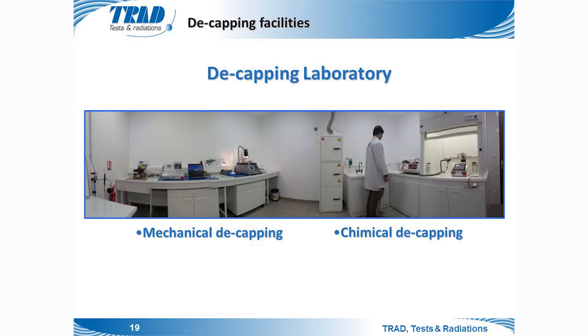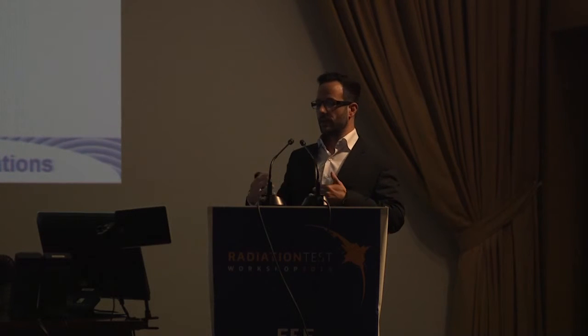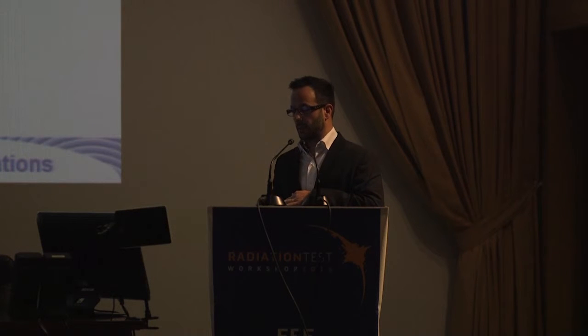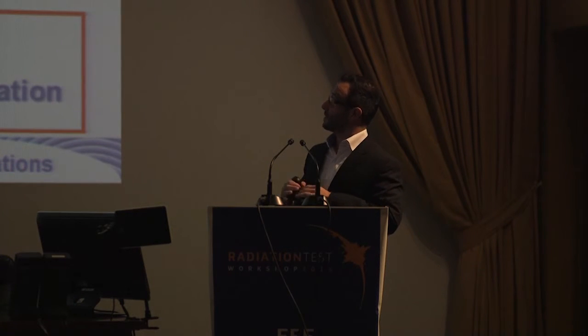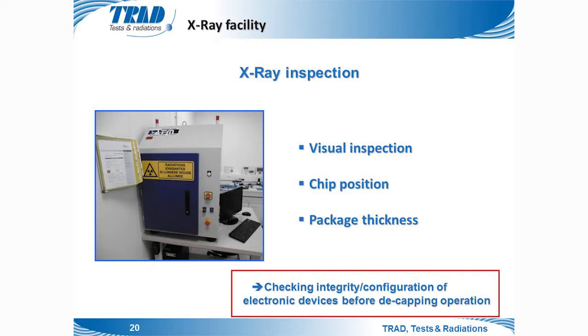So this is why we also have a decapping laboratory. It is dedicated to opening components. You have different ways to open components, with mechanical decapping and chemical decapping. Just before starting any decapping procedure, you have to be sure to know where the chip is. This is why we also have an X-ray inspector.